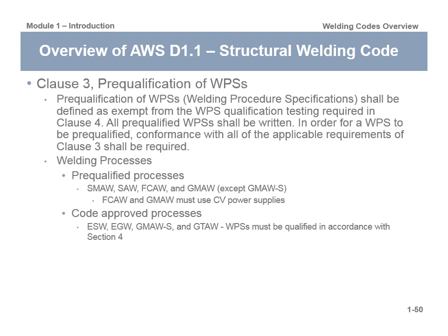So for welding processes, we can use stick welding, shielded metal arc welding. We can use submerged arc welding. We can use flux core arc welding. And we can use gas metal arc welding, except gas metal arc welding short circuiting, because we've got different modes of transfer in gas metal arc welding, and the lowest energy form of gas metal arc welding is the short circuiting.